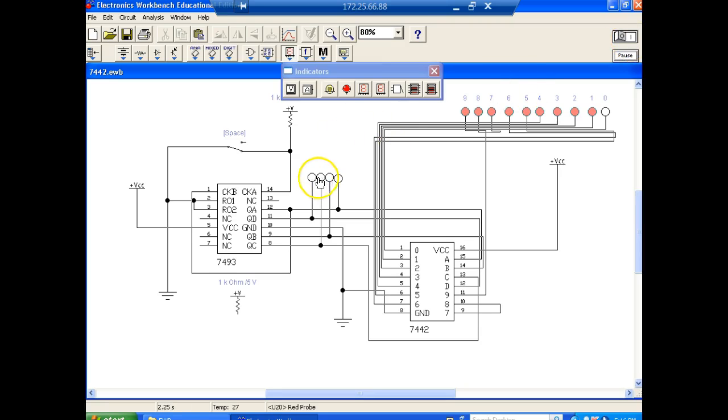And right now my counter's output is 0. Well, which LED is not lit? 0, because that output is 0, right? So now we counted up. This is my count right here, by the way. So, count of 1, which output went low? Okay, so this is a 2, which output went low? Okay, here's a 3. What output went low? 3.